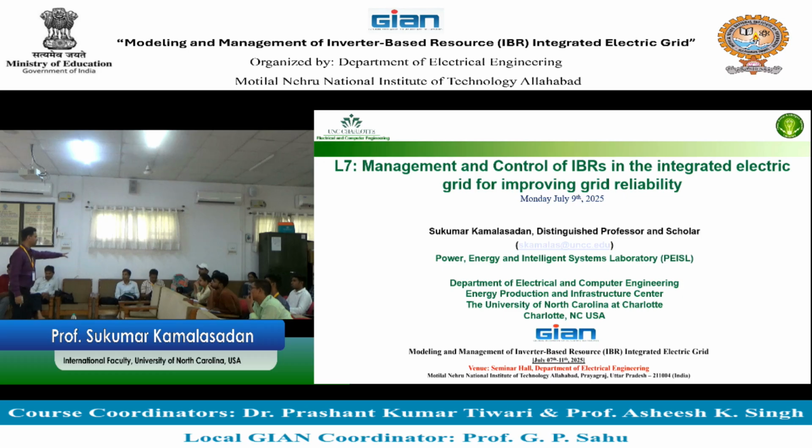Multiple PVs along a long electric grid. The utility will say, a lot of PVs here, it's all changing, so I'm going to put a battery connected to an inverter and to the system. I'm not looking at individual PV control. For the entire area, I'll put the battery and I'll control the battery, right?